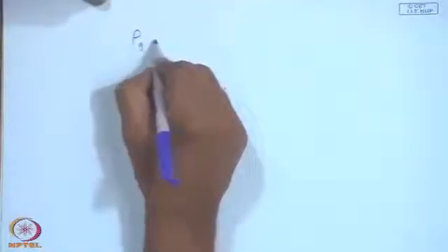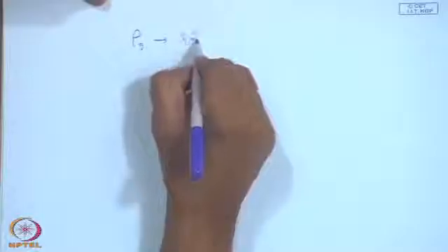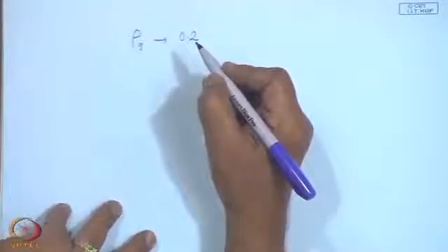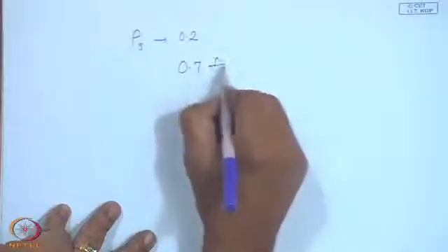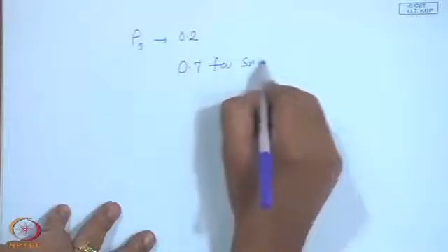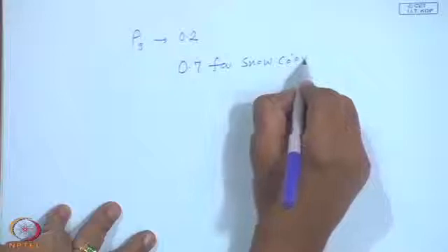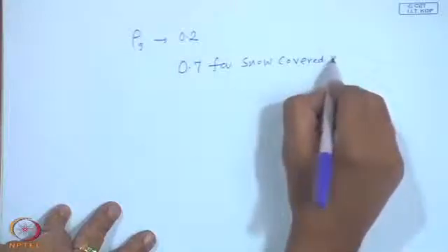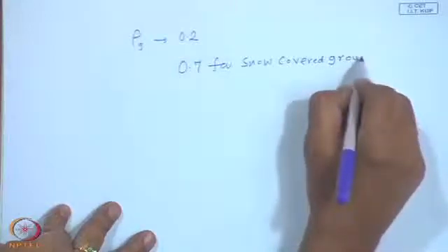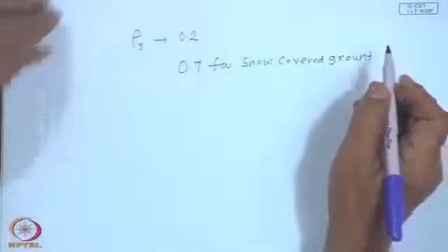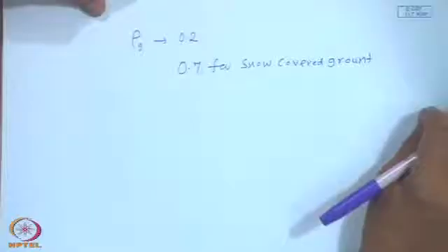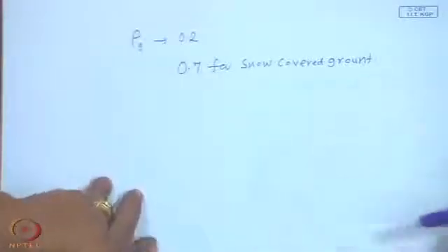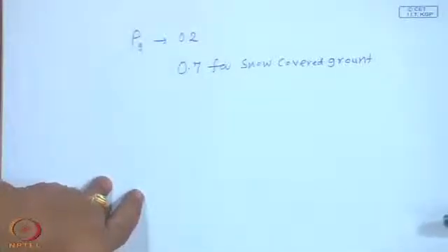And this rho g is typically 0.2 for a ground, and it could be as high as 0.7 for snow covered. Of course, you may wonder if snow cover is there, the solar radiation will be low, whether your solar collectors will be operating or not.